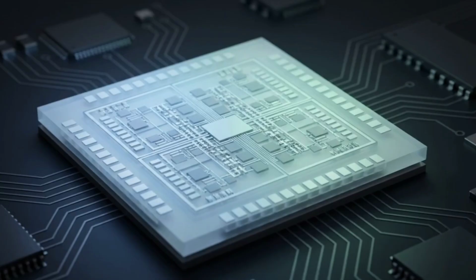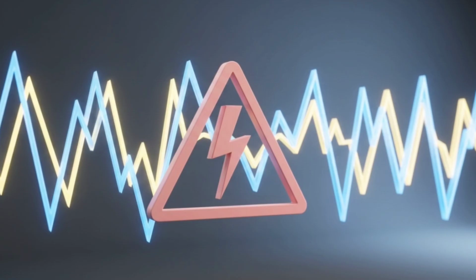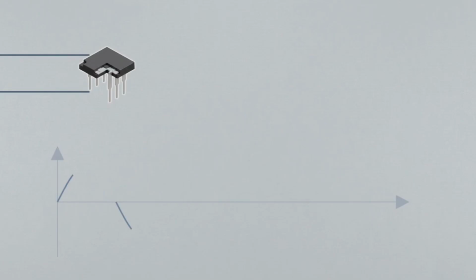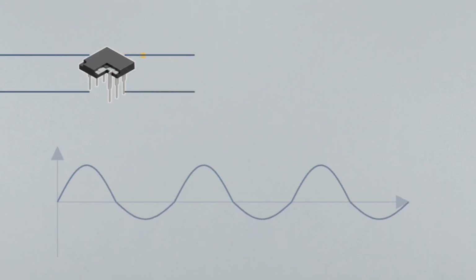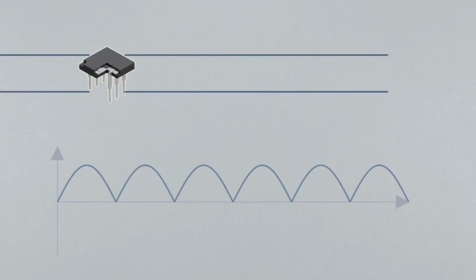This discharge capability directly solves one of the most persistent problems in power conversion, making alternating current usable for delicate logic microchips. Raw AC power constantly reverses direction, which destroys logic components. Engineers route this AC wave through a full bridge rectifier, a configuration of diodes that forcefully flips the negative AC cycles upward into a positive direction.